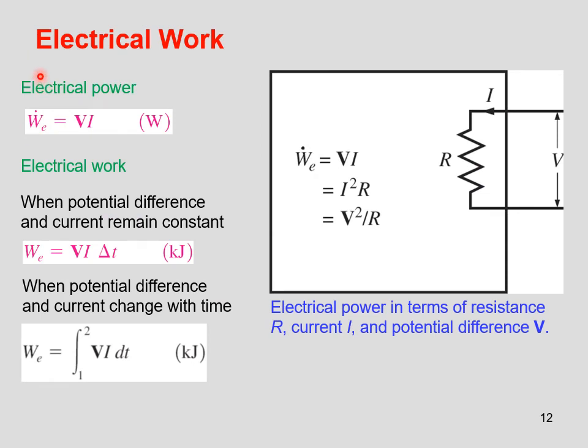So let's talk about the different types of work you can do on the system. The next several slides go through specific examples with equations. The first type we look at is electrical work. Let's say we have a system, and we show our boundary here, and outside is the surroundings. One way we can do work on the system is through electrical means. We can have wires penetrating through the boundary, carrying a current through a resistor. So the power that we can put into a system across the boundary is simply I squared times R.